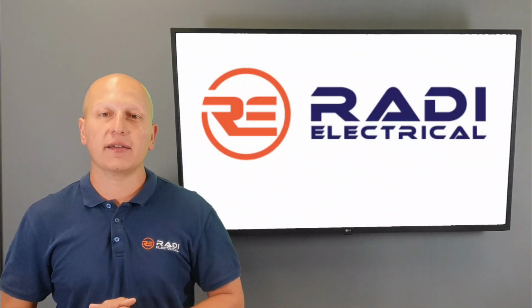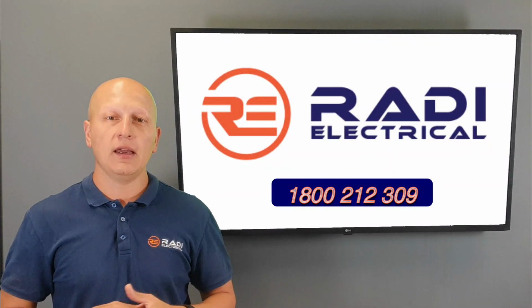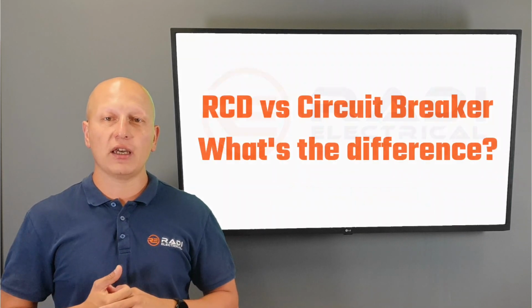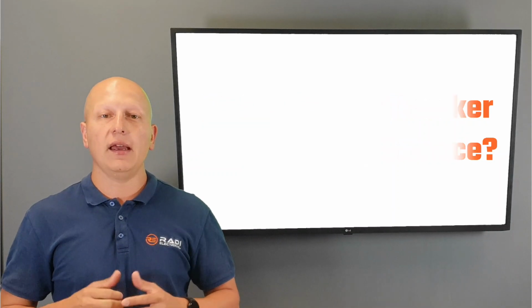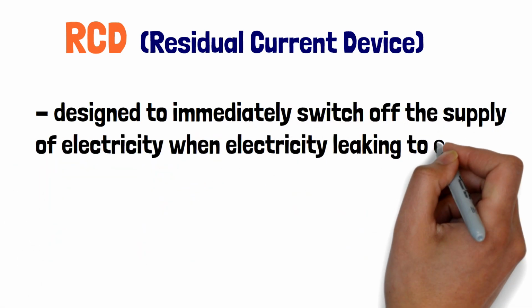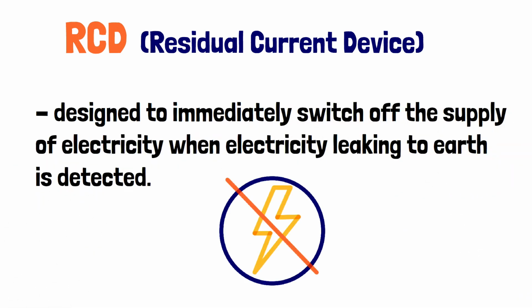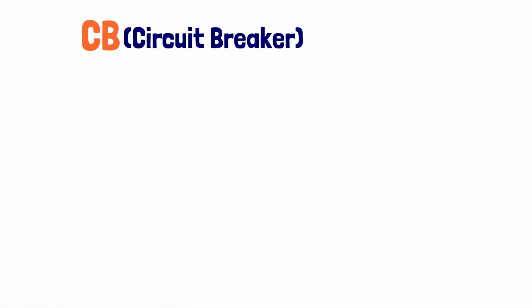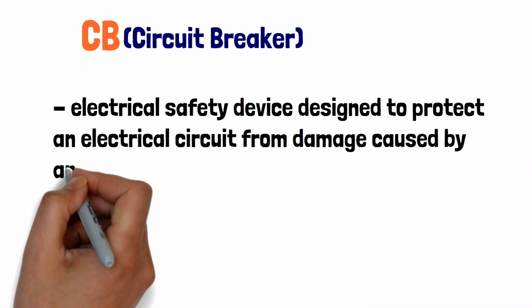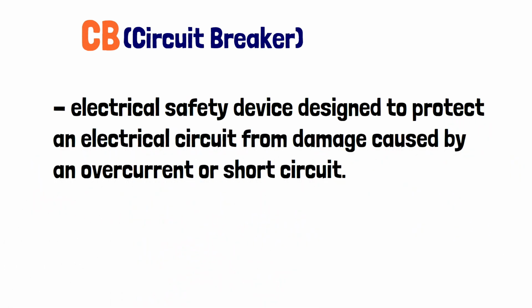Okay, so let's discuss the difference between an RCD and a circuit breaker. It is very important to understand and differentiate the difference between an RCD and a circuit breaker. So, an RCD, residual current device, is designed to immediately switch off the supply of electricity when electricity leaking to earth is detected. A CB, circuit breaker, is an electrical safety device designed to protect an electrical circuit from damage caused by an overcurrent or short circuit.